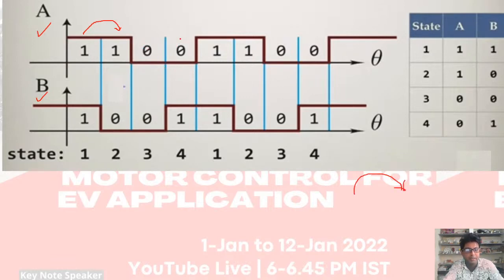Now if you get first the 0 1 sequence, that means fourth state and then third state, or third state then second state, or second state then first state, then the disk is rotating in the opposite direction. Very simple concept. So we have to map it. When we are counting it, we need to do the same thing.